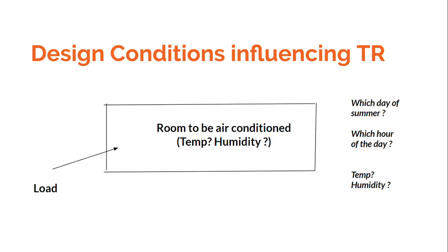If he or she has to feel comfortable, then this would be happening only if the heat balance is proper. And for the heat balance to be proper, you need to maintain a particular temperature and a particular humidity. Now what temperature and what humidity, that is already researched by professional bodies like, for example, ASHRAE, American Society for Heating, Refrigeration and Air Conditioning.